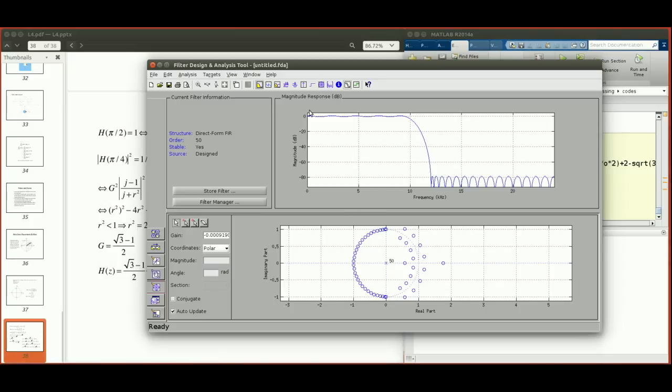And then you can choose to view different kinds of things. So this is the amplitude response of the filter in terms of dB, in log scale, right? And then you can also look at different kinds of things. For example, for now it's amplitude response, and then phase response, and then amplitude and phase response. So if you click on that, it's gonna give you this kind of a combined diagram to show both the amplitude and phase from this particular filter design.